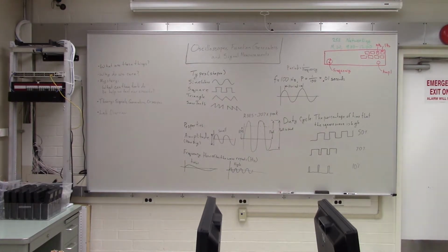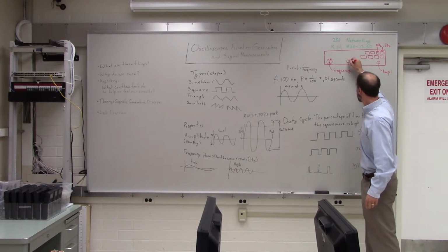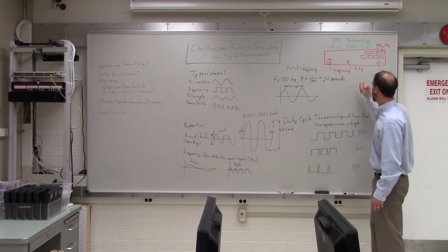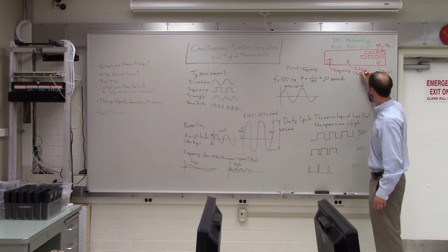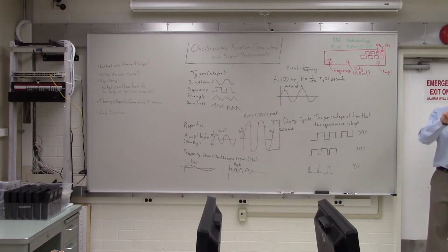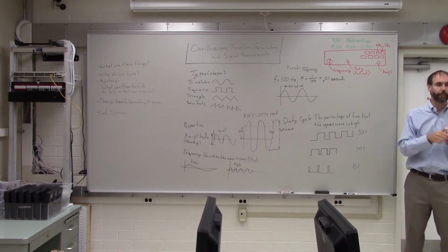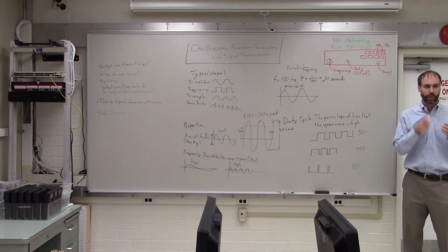And then there's a knob for the duty cycle. The duty cycle is right around there. In order to use that, you have to pull it out. Normally, it's pushed in, and it doesn't have any effect. When it's pushed in, you can turn it left and right, it makes no difference. In order to actually have it take effect, you have to pull it out. And it only works with the square waves?